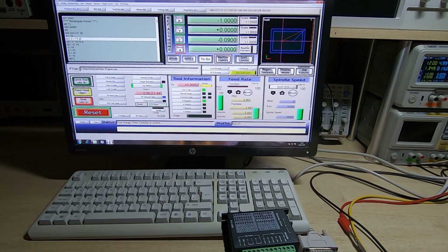You can see it's moving, and we can see the machining process is underway. And normally this will be moving the tool into the material and it will start the milling operation. So we'll run this through until we encounter another tool change request. Let's speed it up a bit so it doesn't take too long. Notice here I've inserted another M6 code. It's not strictly necessary, but I put it there just so that we can demonstrate this process.